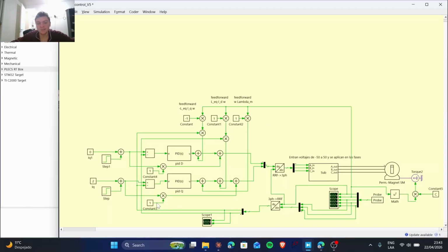We have another feed-forward signal, which is the DC voltage signals. Like if the resistance of the quadrature axis is 1 ohm, and we want to have 10 amps, we know that at zero frequency we will need a voltage of 10 volts. This is what these modules do.